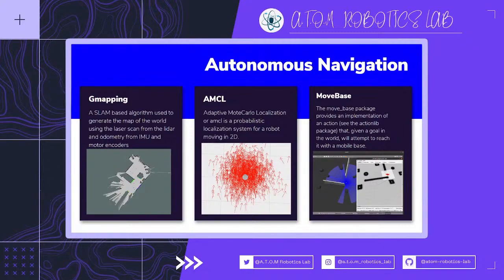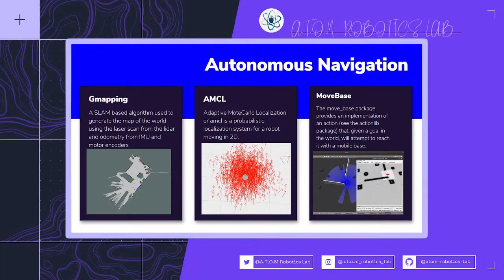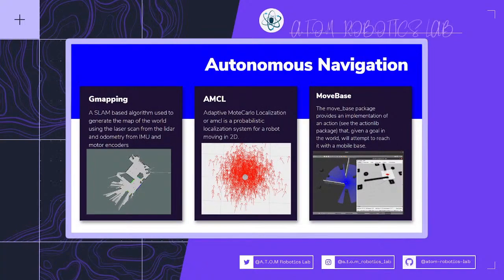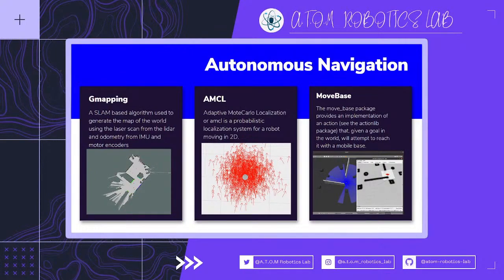Z mapping involves all the odometry that we calculate and maps accordingly. There are different types of mapping algorithms also, like Hector SLAM and Cartographer. They don't require any odom. Basically, you can just hold the LiDAR in your hand and walk around the park, and it will map accordingly without any odometry data. Odometry is basically the location of the bot in the real world with respect to the frame.